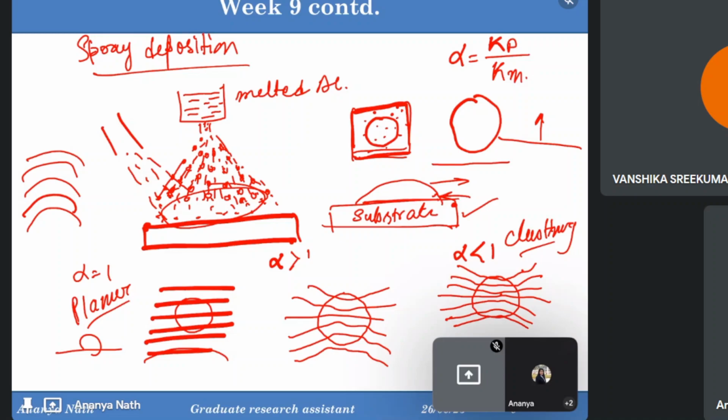Ma'am, I understood. In non-heat-treatable alloys, you said we are not getting precipitation hardening, meaning we are not having any precipitates when we are heating above the crystallization temperature and cooling, right? So there are no precipitations in the 5000 series. So it is not good to go for heat treatment processes, because why are we going for heat treatment? Because of precipitation hardening. We get some precipitates at higher temperature, right? So that's why we are not going for these alloys, because there is no lowering of residual stress as well as no precipitations at higher temperature in these alloys, right?